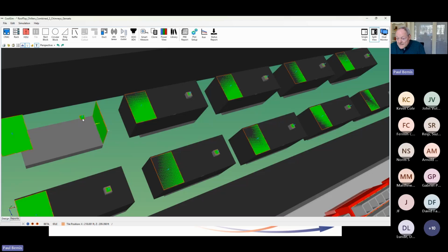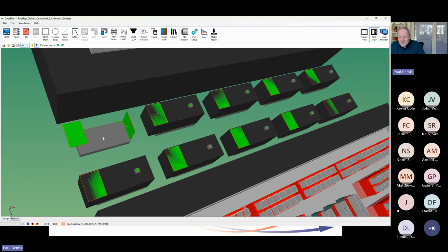That's the exhaust. Now, this would be true even if it was a gas turbine. Same thing. You would have an inlet coming in. A gas turbine would really only have 2 surfaces because the exhaust is mixed in the turbine into the output. So you would have air coming in one side, ambient like that, mass flow rate defined by the rotational velocity of the turbine, which is in the spec sheet. And on the other side, you'd have an outlet. And that outlet, for fossil fuels, is going to run about 1,000 degrees. This one's running at 1022. Sometimes I see them at 950, 1022.